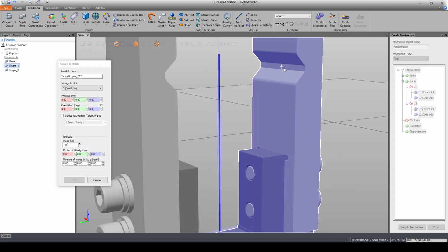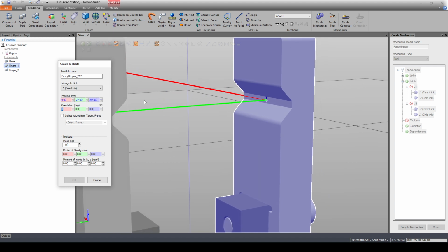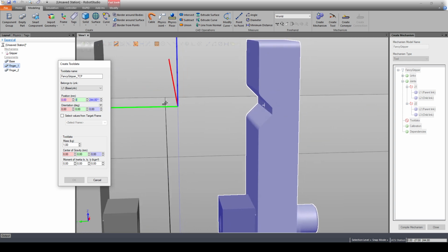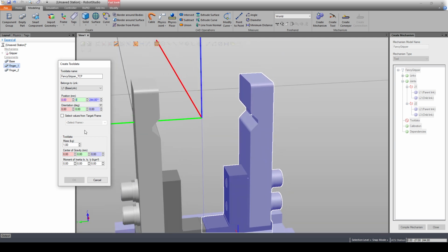And an easy way to find this position is, we can click here at this point. Again, I have the snap object tool selected. Click here, and then you see that it's up in the air but offset some value, y value, and then you can set that to 0 and we will have it in the proper position.